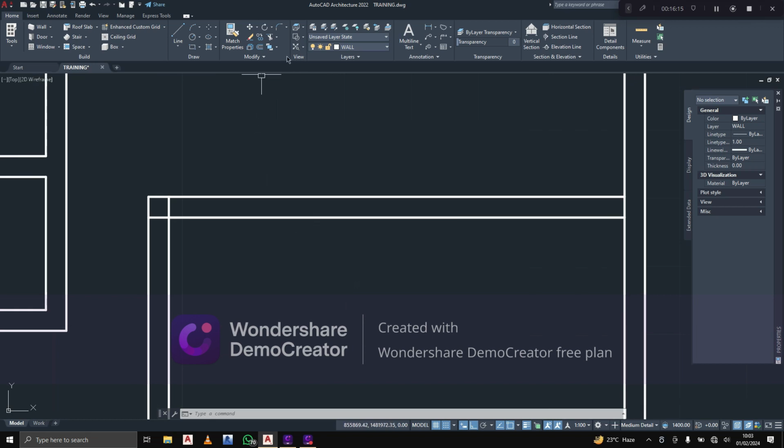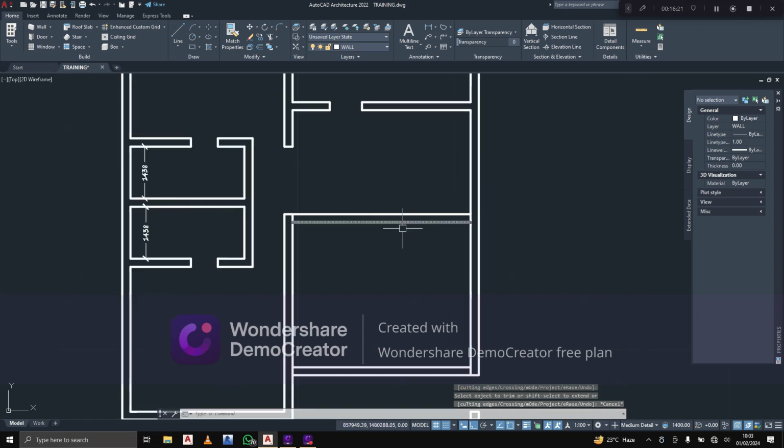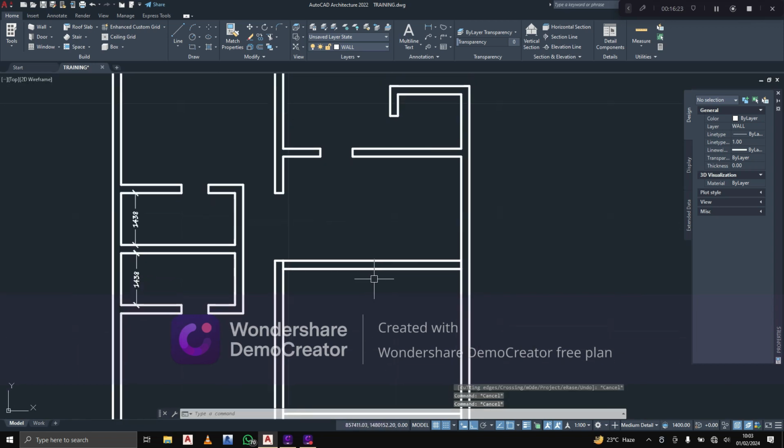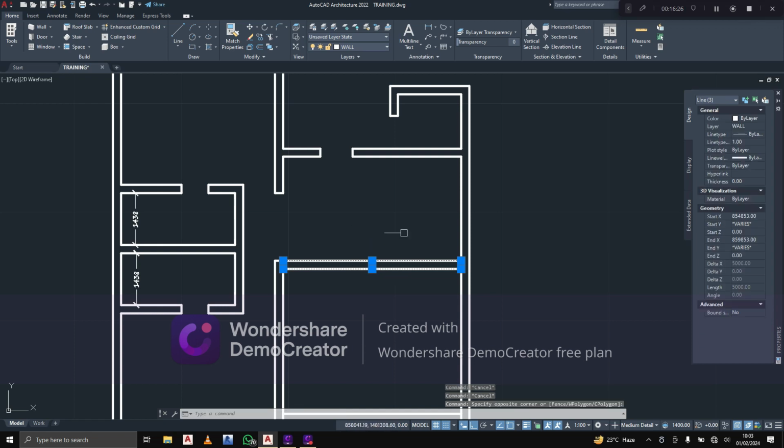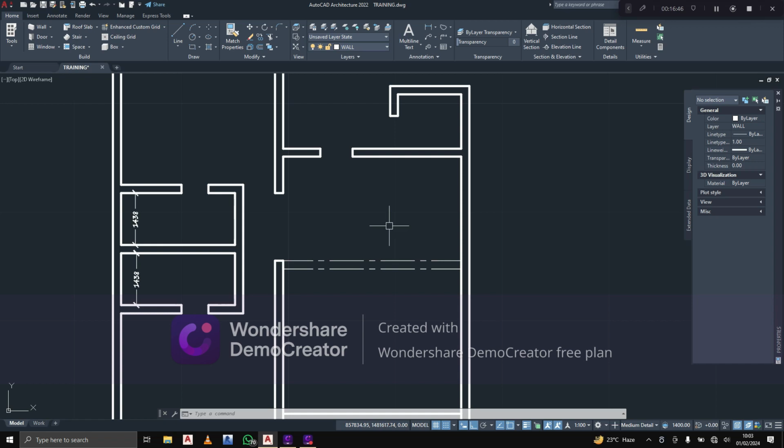You see, this shouldn't be showing like this. It should be an arc that demarcates the dining from the sitting room. So you can just select it and give it another line type. So you come here, you see it is showing broken line already. You can just click that and reduce the thickness, for them to know that this thing is showing upward. It's not really in this level. So just put it to 0 millimeter thickness.